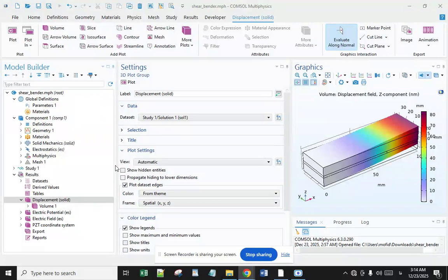Free vibration analysis. Natural modes and frequencies were evaluated for both shear and extension actuation mechanisms. Material data are the same as presented by researchers, and geometric parameters are L equal to 15 millimeter, H equal to 2 millimeter, T equal to 0.5 millimeter, DC is 11 millimeter, and A is 20 millimeter. The first five natural frequencies are given in this table for both actuation mechanisms.